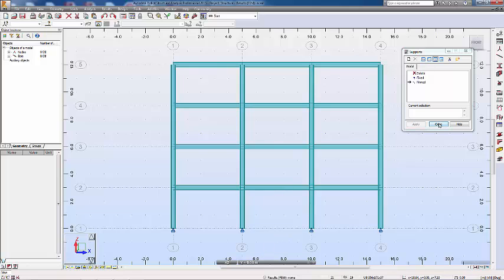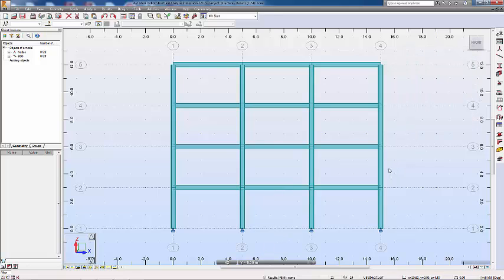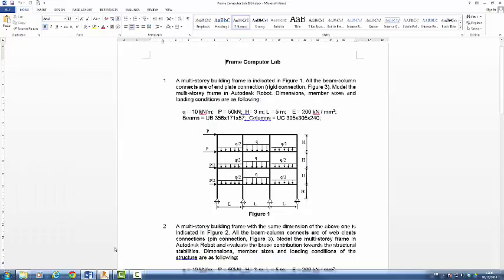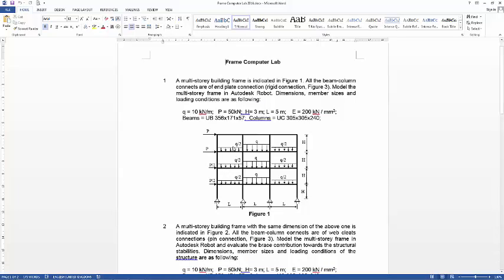And so once finished, you can close this window. At this moment the structure has finished, so we need the loading on. To apply the loading, what we're going to do is define a dead load, in which all the vertical loading we define as a dead load, and then all the point load, then we can put in another case, we call it live load. Of course it should be the wind load or some of the other loadings, but we put it in the live